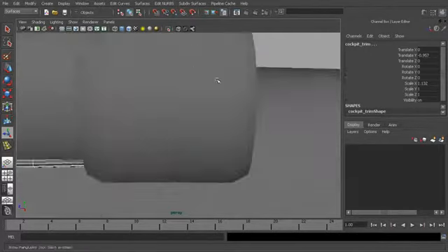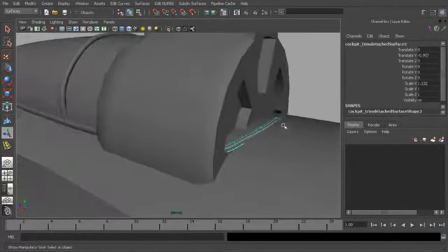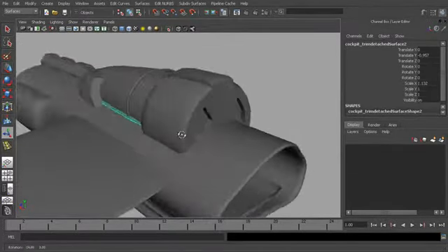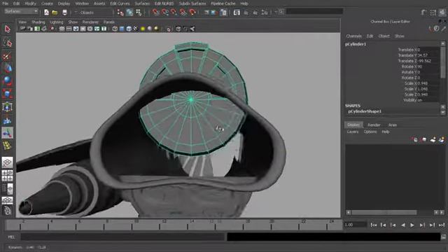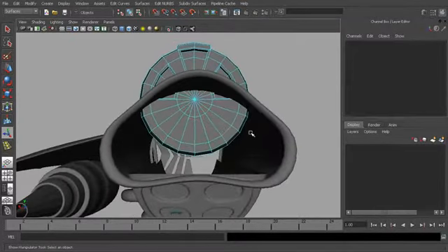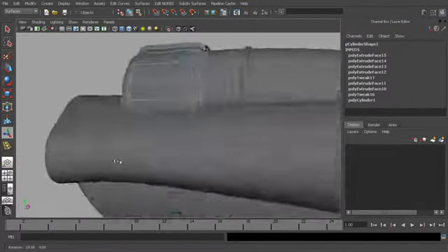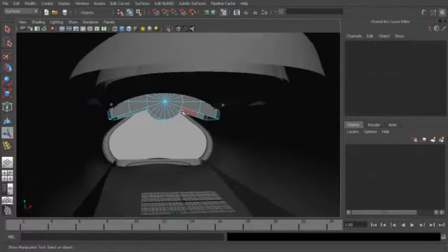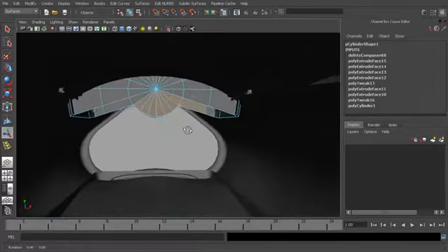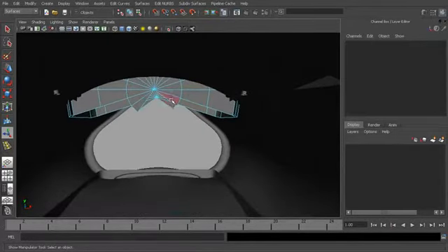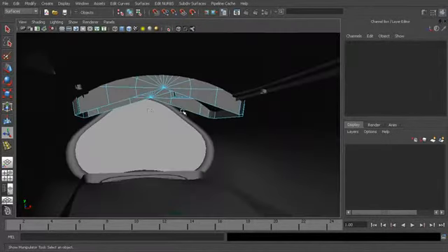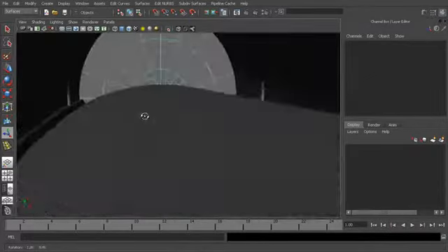Okay, we'll turn off view selected, and now we've got these all separated. So I can delete those and we're left with just the piece that we need. Okay, same thing here. We don't need all of this geometry down here, but when it's a polygon, all you have to do is go in and select it and then you can delete it. So coming in here, selecting those pieces that we don't need allows us to save on polygons. We don't need all that detail in there.